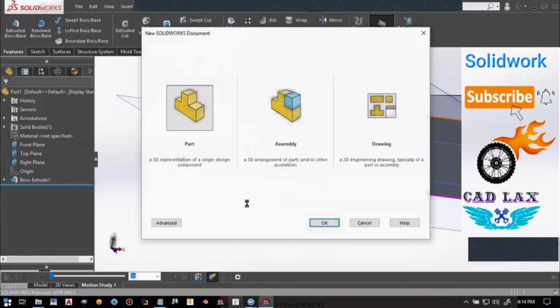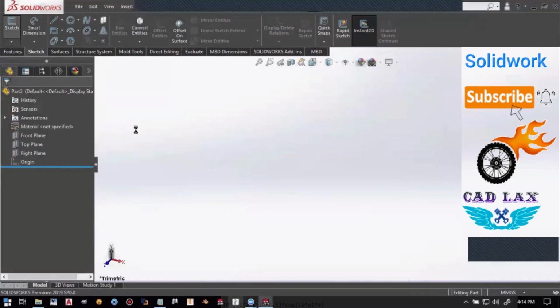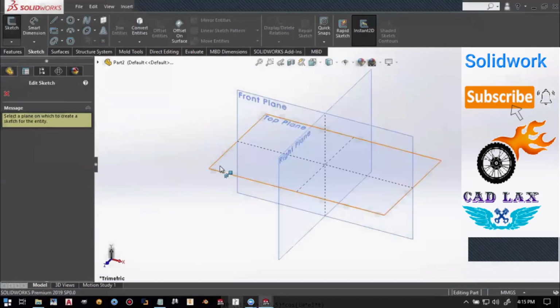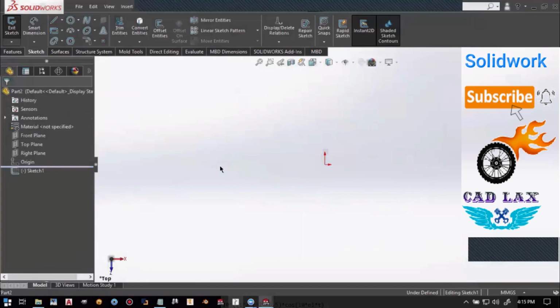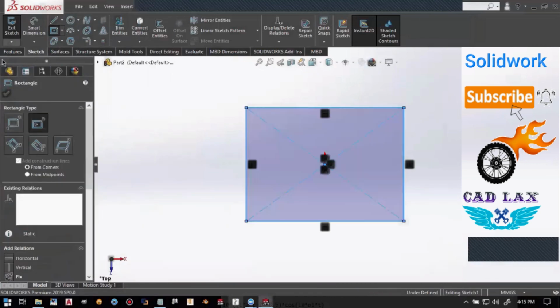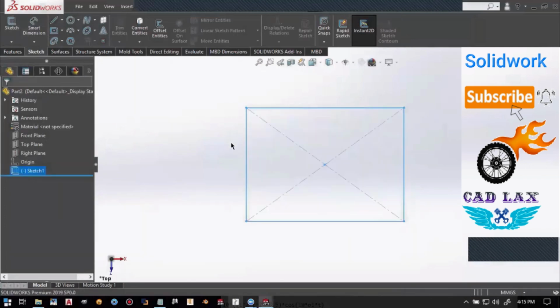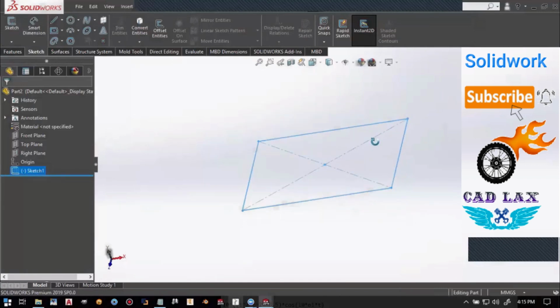I'm creating another sketch. There is a technique in SolidWorks called multi-part modeling. Do you know about that? In multi-part modeling, in a single part module or single template, we can create multiple solids, and these solids can be saved as different parts.